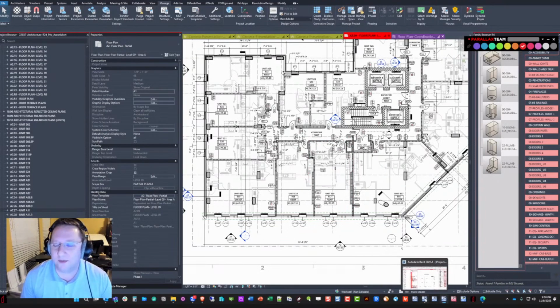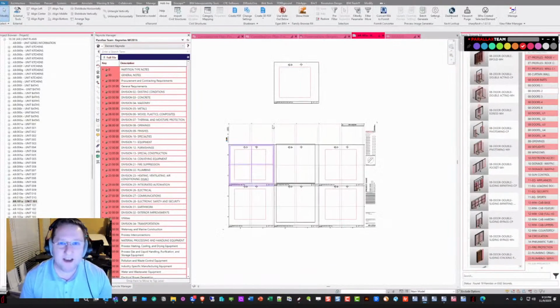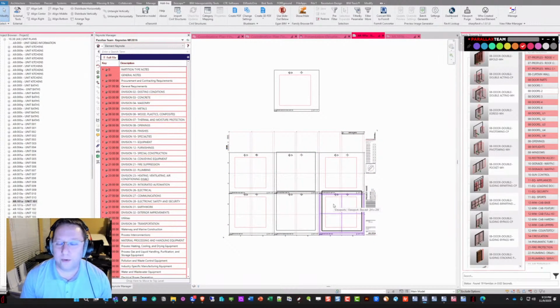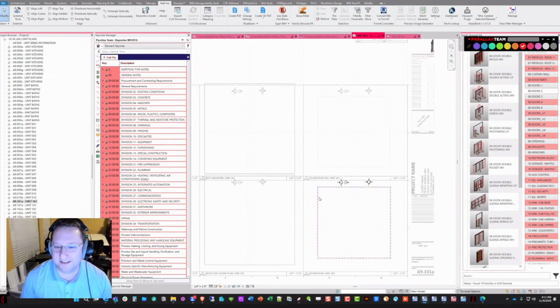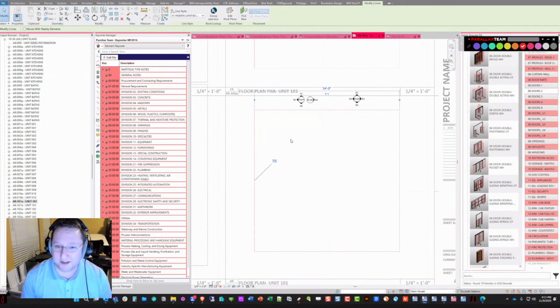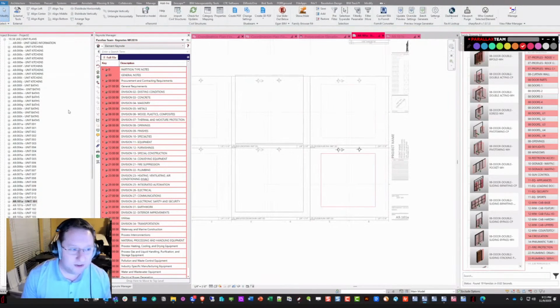So here's the thing: whenever you hear me say something ridiculous, my only ask for the whole BIM community is, before you judge, do it on a job. Then come back and judge. It's fine. We will use model lines around the interior of all the units. So in the cloud, in the unit cloud? They are part of the unit group. Got it. So they will populate the whole building. They will be sitting in the unit cloud, and there will literally be model lines that show the interior face of where that unit ends.